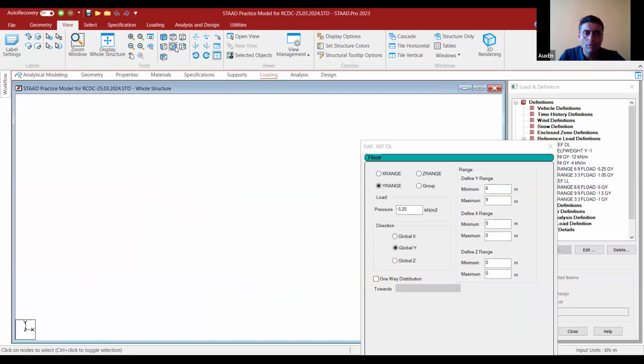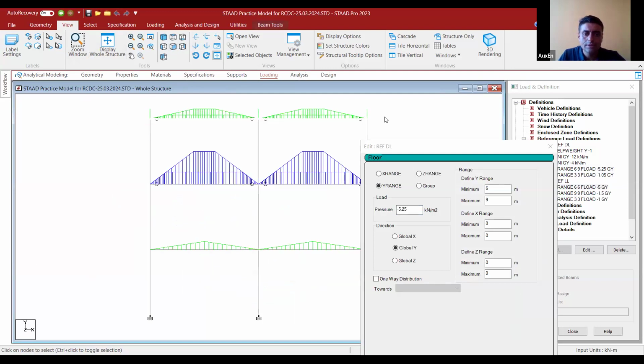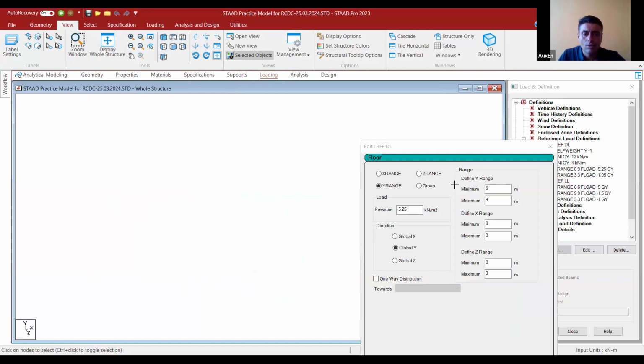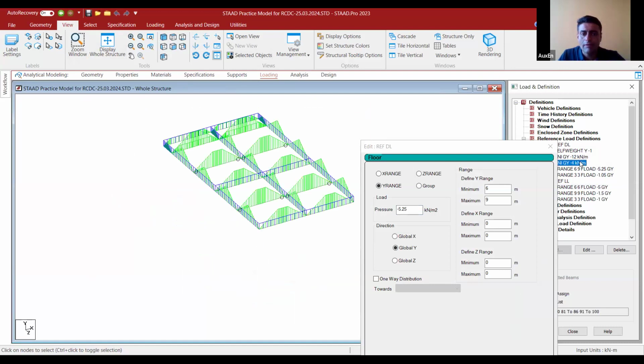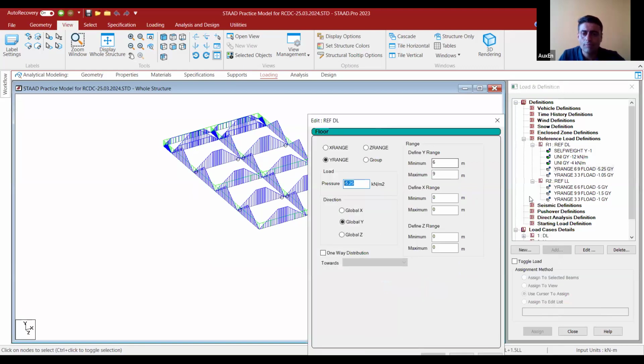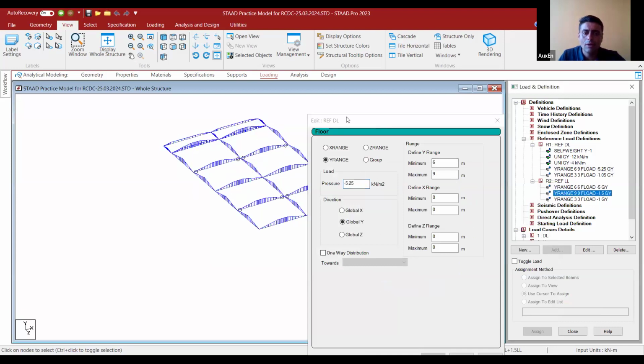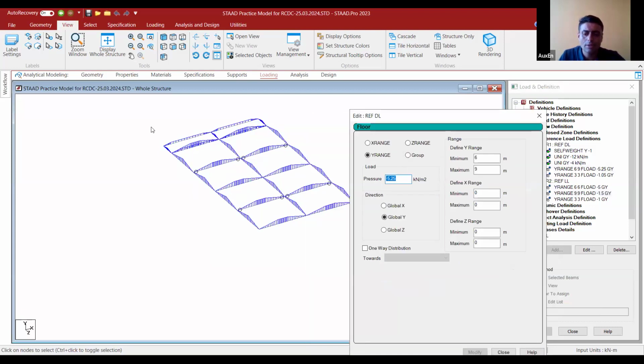And if I talk about the roof floor, what I have done is that at the roof floor, we have applied a 4 kilonewton per meter brick wall load. Let's say it's the parapet wall load. And we have applied the parapet wall load on these beams as well, on the cantilevers also. And this is the floor finish plus slab self weight, 5.25. The live load applied on the roof floor is 1.5 kilonewton per meter square, assuming it to be accessible floors.